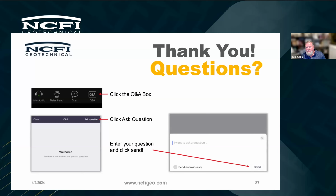The single component can also be used for those types of projects if the soils are right. The thing about single components is you have to have a non-cohesive, sandy type soil that it's going to be able to permeate into. You're not going to push single component into clay, but your need in the case of clay is not as high, and chances are the clay will hold itself up. But if you've got loose soils that need to be stabilized for excavation, then there are options both ways depending on the situation and the subgrade.